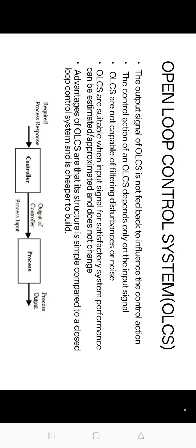The control system circuit diagram is shown in the figure. In this, R(t) is the input signal in the control system. The output remains unaltered for a constant input. In case of any discrepancy, the input should be manually changed by an operator. An open loop control system is suited when there is tolerance for fluctuation in the system and when the system parameter variations can be handled irrespective of the environmental conditions.